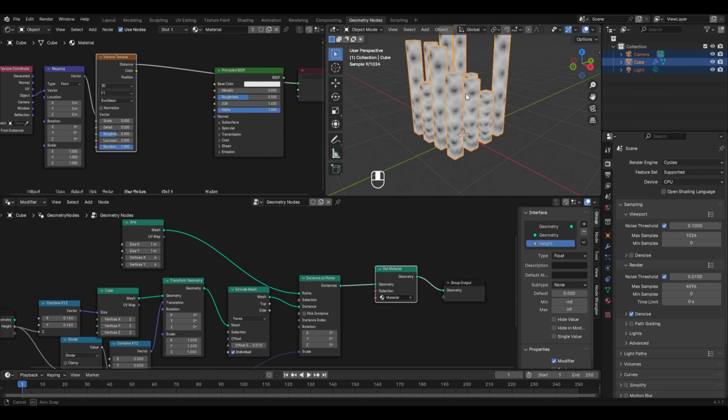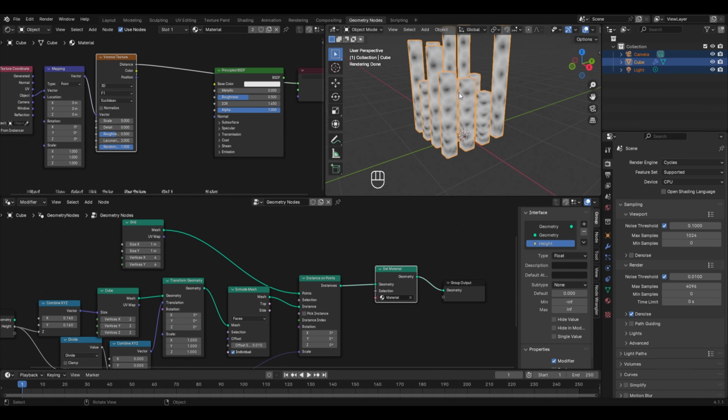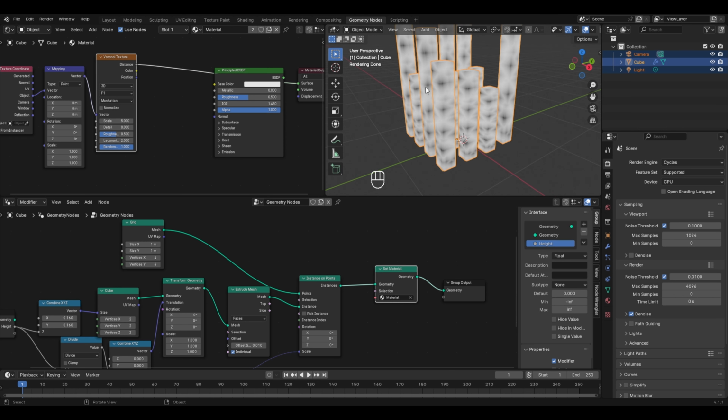Now here we are having some random spot-like texture on our buildings, but we really don't want that. To change the way it looks, click on this option where Euclidean is selected and change it to the other types. With the second option selected, which is the Manhattan, the texture looks like this, and this is also not perfect. So we'll go for the third option, and let's also try to change some settings here.